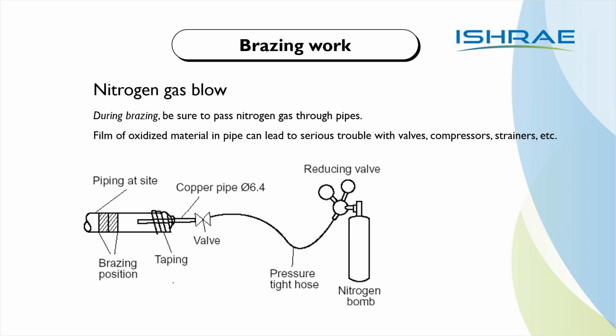Then this, I don't think even today, even though it is the most important part to follow while brazing, nobody does this. This process is known as bleed off brazing. It is the most important procedure you need to follow while installing a VRF system. You need to follow this procedure called bleed off brazing. Now, if you have to do this bleed off brazing, you need to have a 2-stage regulator. Always use a 2-stage regulator.